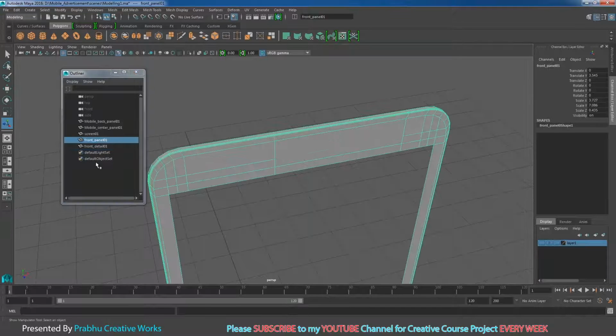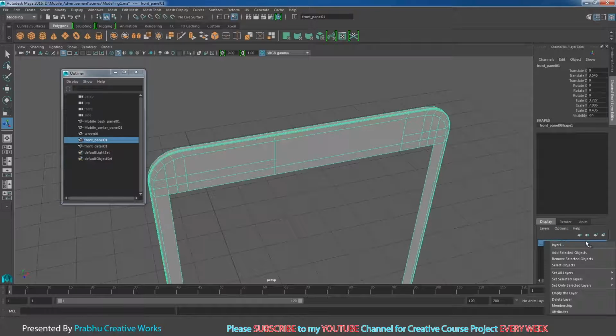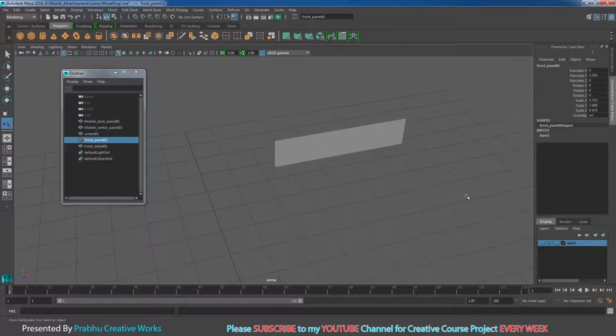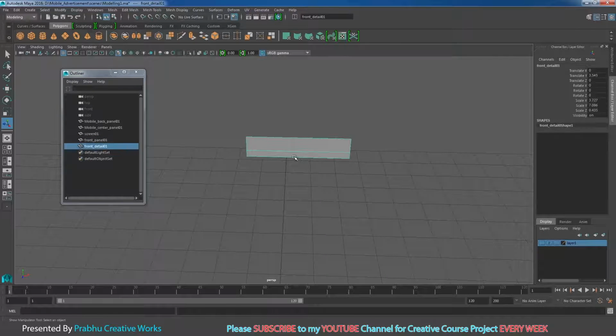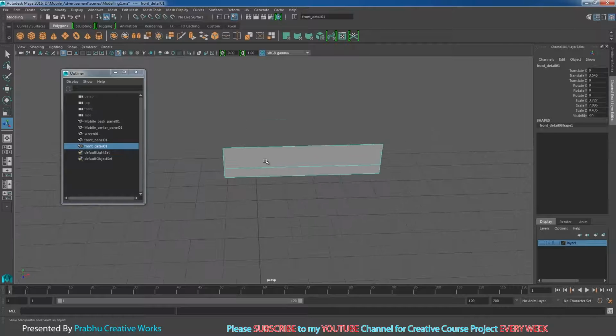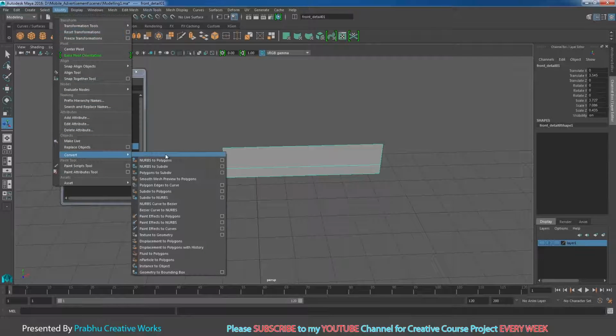So now I select the front panel 1, right click on this layer and choose add selected object. So now you have only visible this front detail part. So now I want to convert this mesh as a NURBS. So in modify convert we have only sub D to NURBS option. But it's polygon, so there is no polygon to NURBS option.